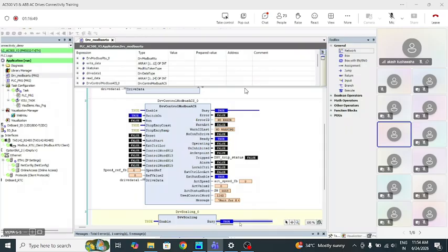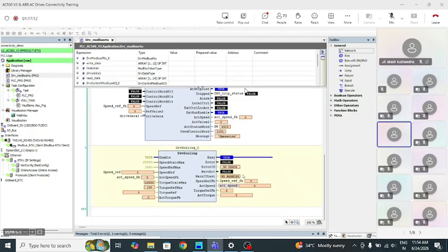So I will switch on. You can see here the control word, the drive is ready and it is ready to take the start command. Wait for run input. So I will give run. Okay. So you can see operation. Operation means the drive is running. Here ready, operating and set point.